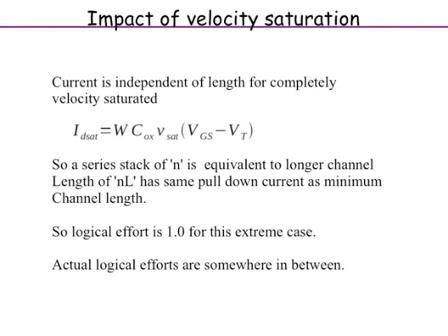That is why for a NAND 2 we had double the width, because we said length is double effectively, so overall width of each one should be double. Here, when I put the series stack and there is no degradation in current, why should I double the width? I'll leave the width the same. I'll use the same size one transistor for a series stacked gate also.